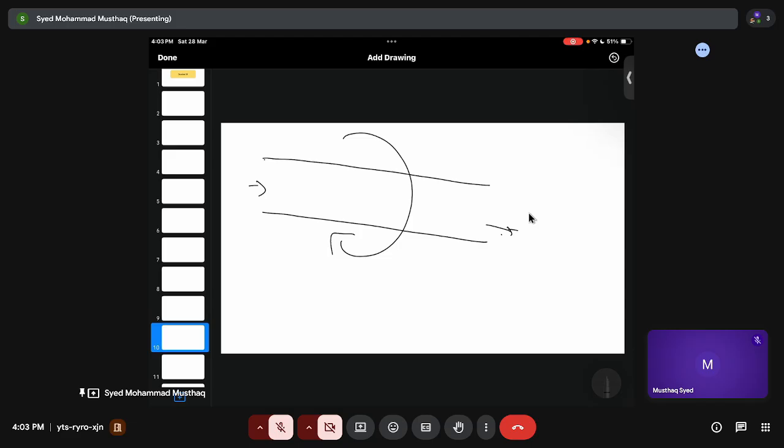And in the rotary hearth, it rotates along its center, so it is not inclined. It is a cylindrical furnace, the same, but the height is small and the diameter is large. And in the shaft furnace, the diameter will be small and the height will be large. So that's the maximum difference that you will find in these furnaces.